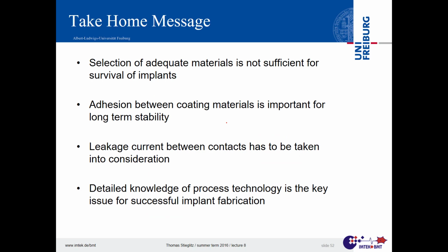For you, the take-home messages: you have to select adequate materials, but that's not all. You have to check adhesion, and you should also consider the leakage between contacts. It's not only the leakage inside and outside of the package. If we have some adjacent lines, if they short-circuit each other, that's also nothing we want to have. And the devil is in the detail. That's probably the best summary here for all the assembly and the materials and bringing things together.